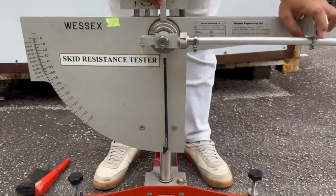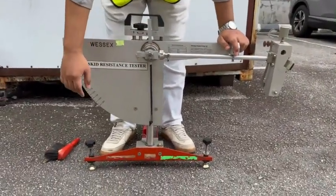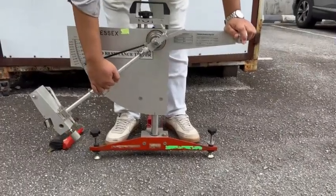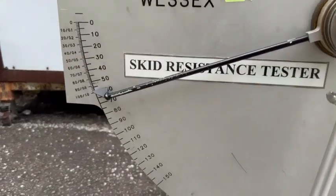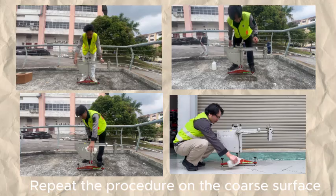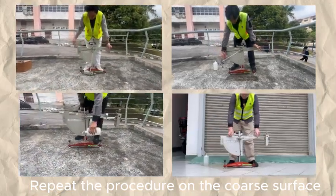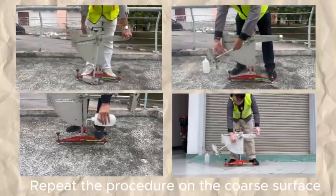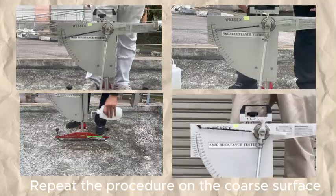But before you run the test, you have to reset to the 0 value first, and then let it swing and record the value on the skid resistance tester. And also, don't forget to spray water onto the surface, because we want the wet condition of the pavement surface.